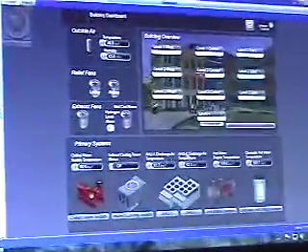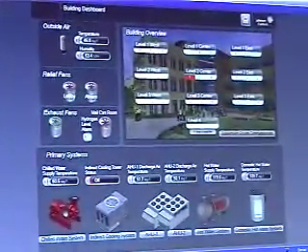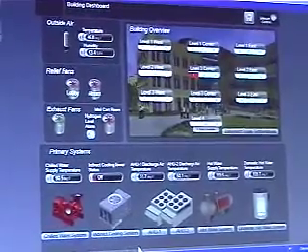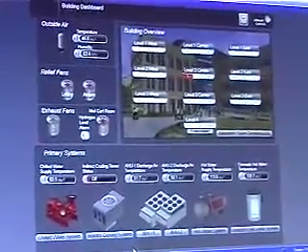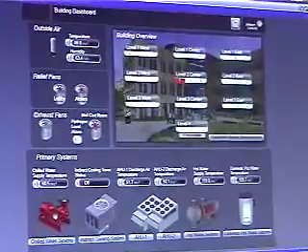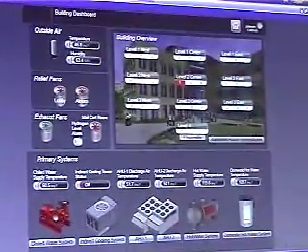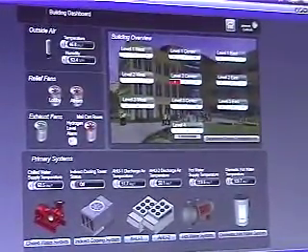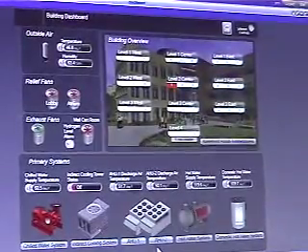Here you have your 2 air handlers, air handler 1, air handler 2. As far as controllability and everything, they're completely identical. The really only difference is air handler 2 is a bigger fan, which has more of a fan wall with 6 fans, 2 VFDs. Air handler 1, just one really big fan.